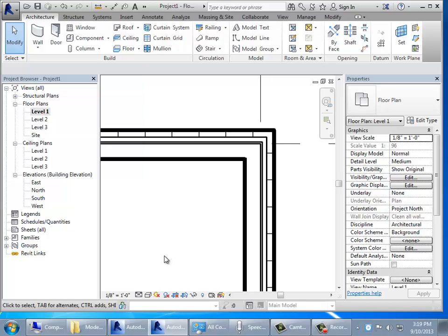When you're doing the detailed design, you want to show the fine, and in some views you really want to see all that, but it takes a little bit of time to render all that stuff. So where you care about seeing detail, turn it up. Where you don't care, if I'm looking at this from 300 feet away at a very high level scale, I don't care about the detail of what's happening in that wall. I actually confuse things. I don't want to take the time to render it, so leave it coarse.